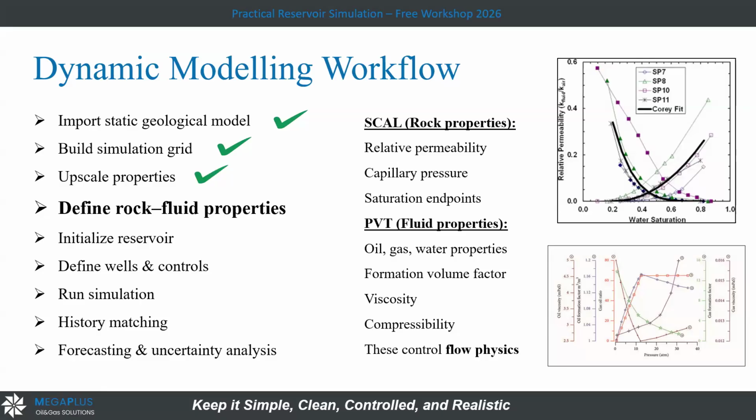So we must now understand that yesterday all of the properties that I inserted were static. They're not changing with pressure. But in dynamic, everything changes with pressure, it changes in time step. This is why it's called dynamic. So what changes with the pressure?